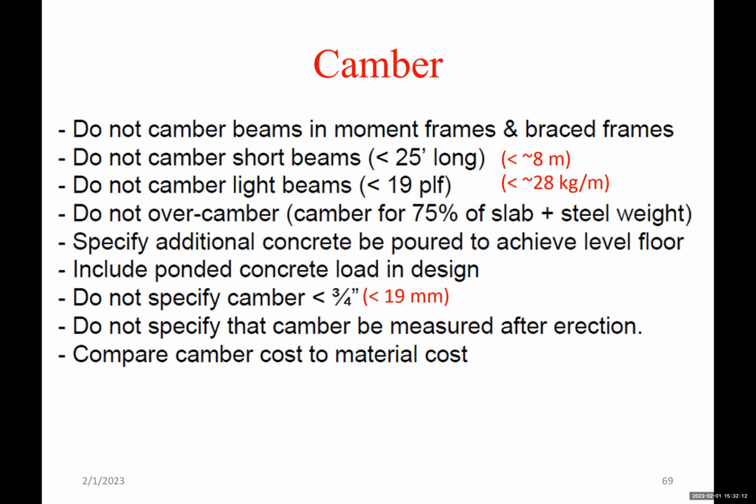Compare camber cost to material cost. Ask how much it costs to camber a beam versus if you increase it by 1 or 2 sizes, what is the difference in the cost? Is increasing the size cheaper than camber? Then do it. If not, you can camber.